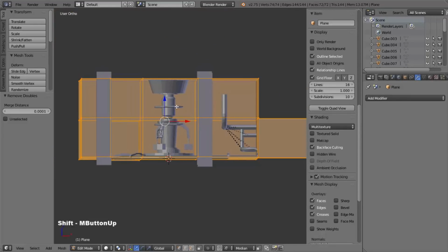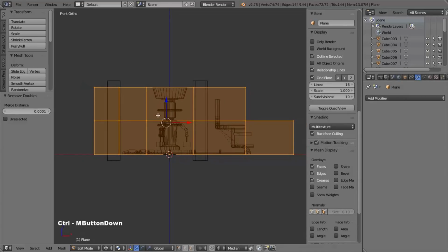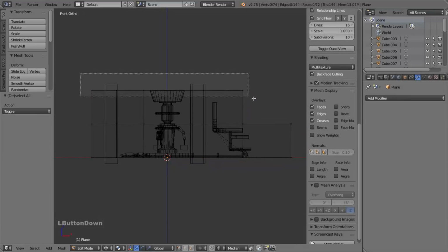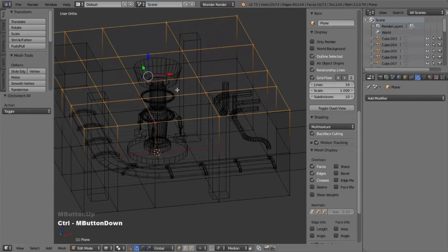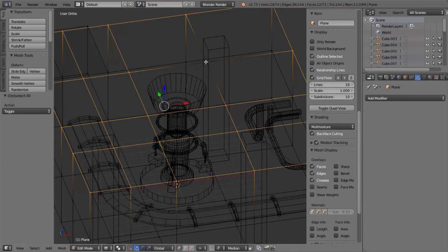It's very blocky at the moment. So I'm going to go into wireframe view and front view, and then I'm going to drop my current selection and then select all of the vertices that make up the top. And the vertices that make up this face that we cut in earlier on in the center, I'm going to hold shift and deselect those.